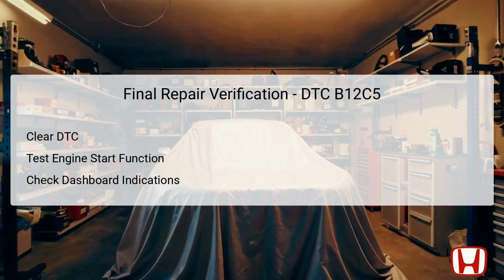After completing the necessary repairs or component replacements, proceed with the final verification process. Start by clearing the DTC through the vehicle's diagnostic system to eliminate any stored faults. Once cleared, test the engine's start-stop function to ensure the switch operates as designed.